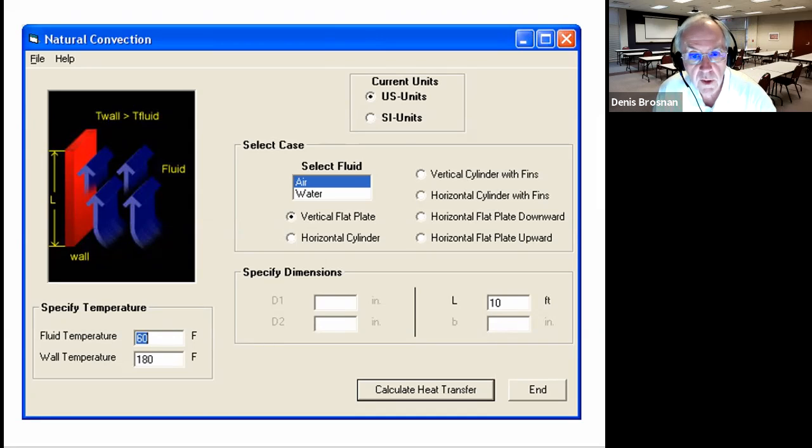And so we're in Hauck eSolutions. We're looking at heat transfer from a vertical plate. So there's a plate that's hot on the outside. We've had to select a fluid for the surrounding atmosphere, which is air. We've selected a vertical flat plate. The little program shows that we're going to have air that's heated by the presence of the plate, and the air is moving upward by buoyancy when it's heated. So this is how the Hauck program calculates convection heat loss from a furnace shell.